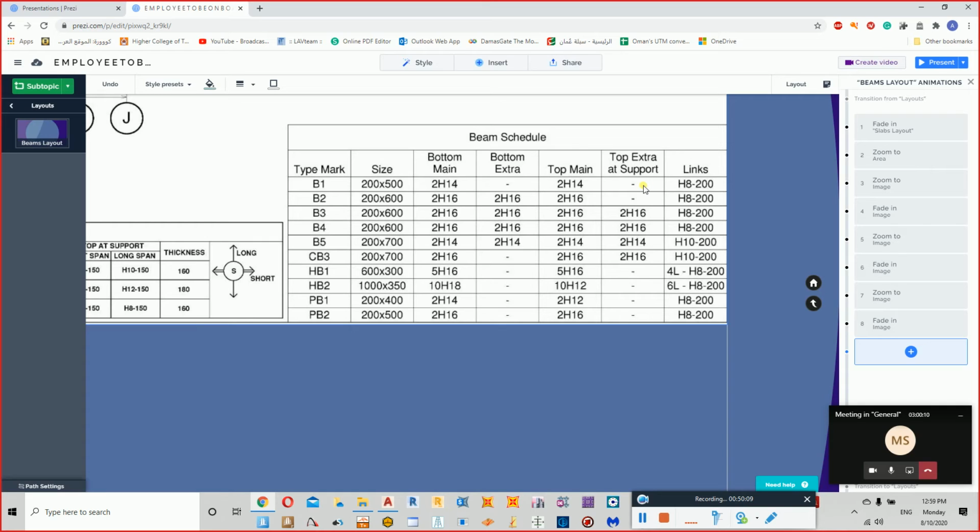If we see the parabolic in this way, we have this portion which is the maximum, this side and this side. Normally we provide one reinforcement at the top. If it's sufficient, then there is no need for extra reinforcement at the top, like beam number one. If it's not sufficient, then we need to supply extra reinforcement at the peak. This is sufficient here, this is sufficient here, and we apply extra reinforcement at the top.